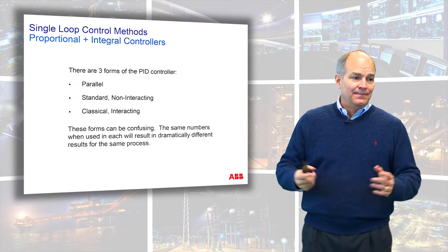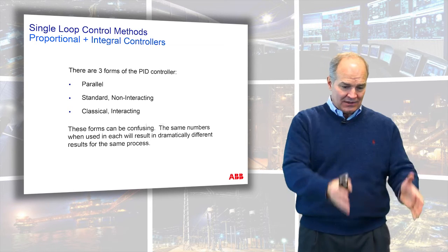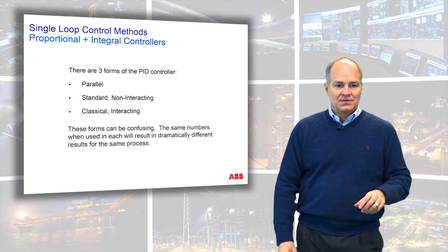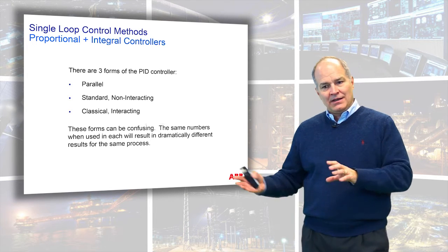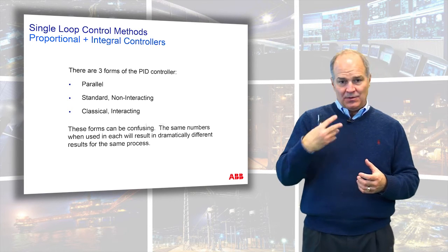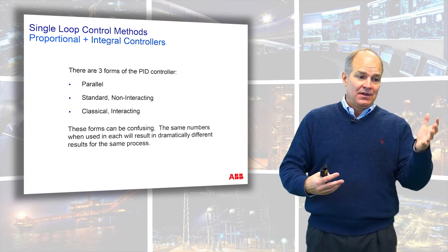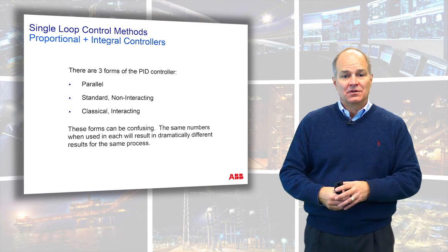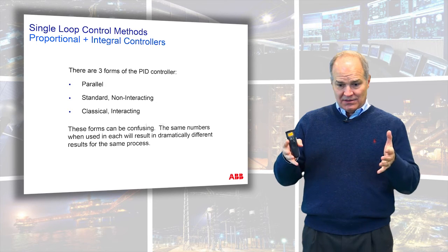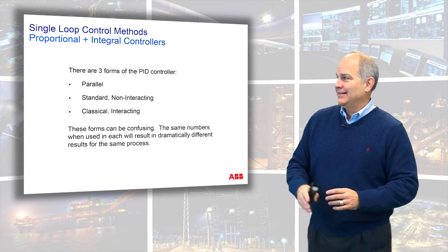it is. There's been so many, I've seen this happen more than once, where somebody will have had a particular brand of controller and they got really good at tuning and setting up the tuning numbers. And so they were getting ready to upgrade to a new vendor of controller. And so the expert in tuning said, well, I know what to do. He copied all the PID algorithms or parameters from the old controller and put them all in the new controller. When the plant started up, things oscillated all over the place. They brought in the tuning expert and he goes, they're the same numbers I've always used. This system's broken. And that's not the case.